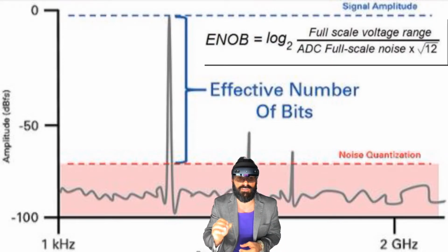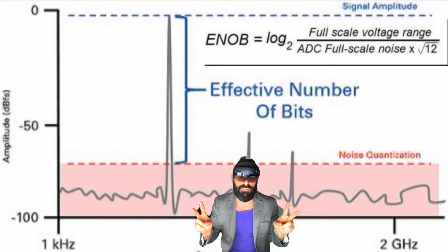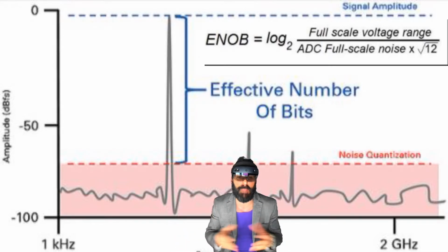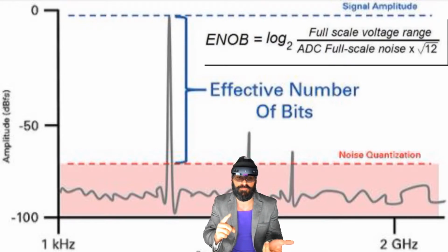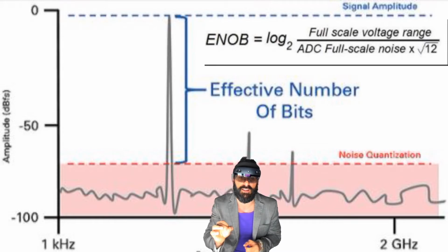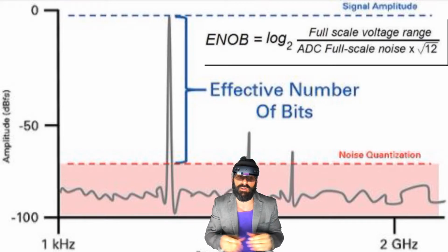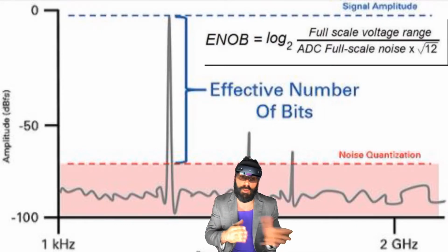Now, as we look at this evaluation of the data acquisition system as it performs in the real world versus what the manufacturers say in their lab, we have to test all of the cables and connections and operational amplifiers, and we have to consider the front end of the data acquisition system: the ADC, the multiplexer, again the programmable gain operational amplifier, and the sample and hold amplifiers. All of these individual circuits will affect the digitized output from the ADC, and any and all nonlinearities such as noise, distortion, quantization, and other types of anomalies will sneak into that front end of the unit. It may only be in one channel or multi-channel. It could be across all.